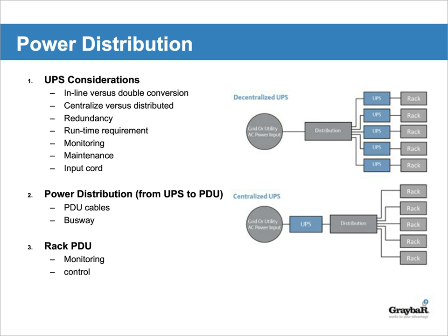The other important consideration here is centralized versus distributed architecture for the UPS. And this only applies if you're talking about a location that has multiple closets or multiple rooms, right? If you have only one room, that's not a problem. It's of course centralized. But if you have multiple rooms in the same building, you have options, right? You can either get a larger UPS in the central location of the building, or you can put small UPSs in every single room.